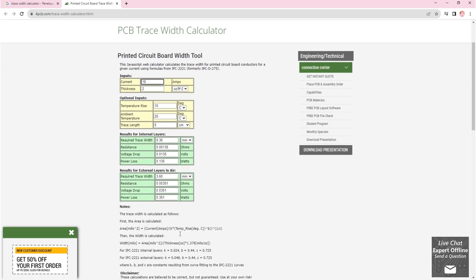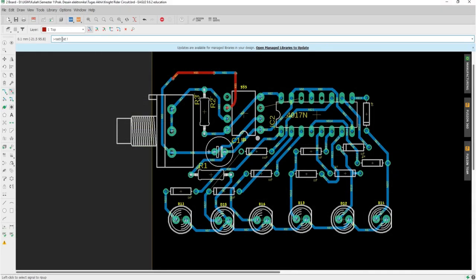After you're done making the PCB design, you will most likely manufacture it. So, it is better for you to understand your manufacturer's specifications first. Before you start laying down a copper trace, take the time to give your manufacturer a call or shoot them an email to see if they have any specification requirements on minimum trace width, trace spacing, and the number of layers they can handle on a board.